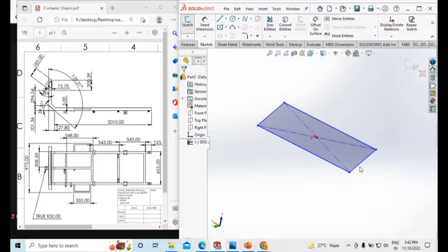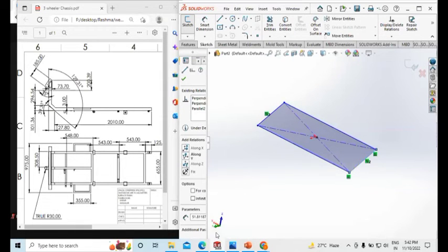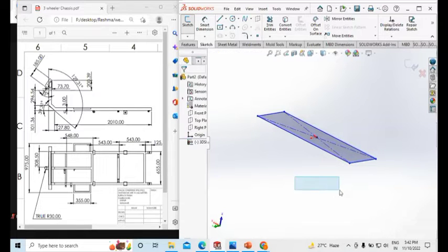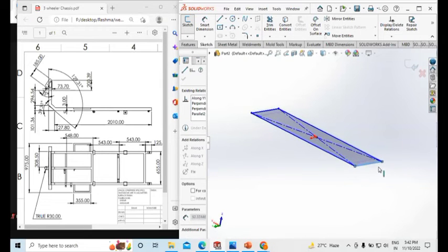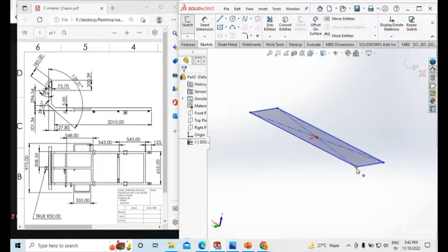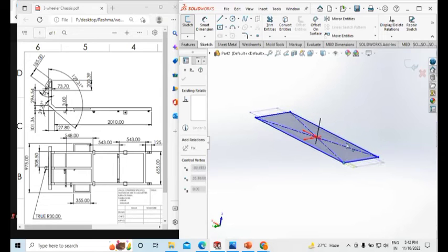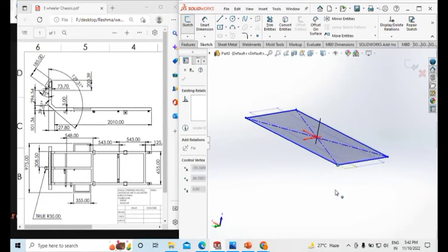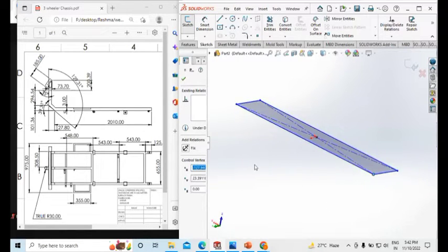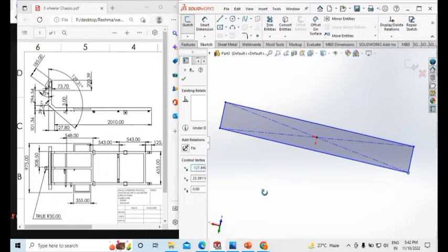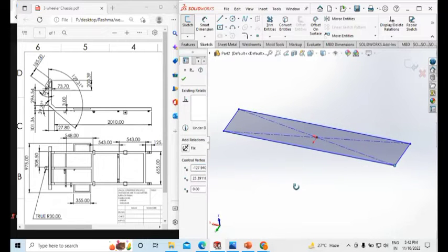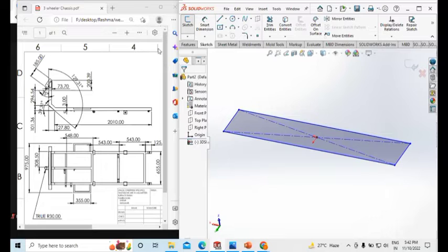Okay, and this I'll also take with the help of the y axis. So let's click on that and go for the y, and now it has taken. Now see, is it movable? No, it's only reducing and increasing the size of my profile. Then one by one we have to restrict the degrees of freedom.